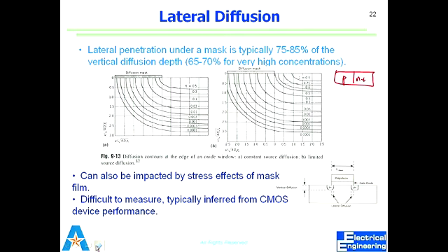The same is true for ion implantation. For polysilicon, what we do is in situ deposition. Once we are depositing polysilicon, we have dopants that go inside the furnace, so we dope polysilicon while it is being deposited. Not only diffusion, ion implantation also puts a restriction on the temperature. So ion implantation doesn't make sense for polysilicon, because we can dope while we are depositing it over the whole substrate.